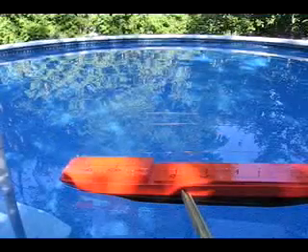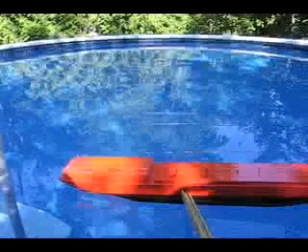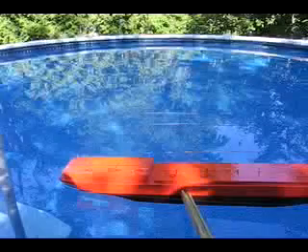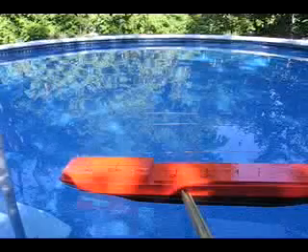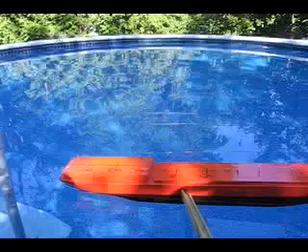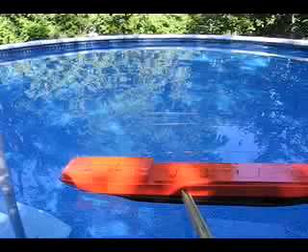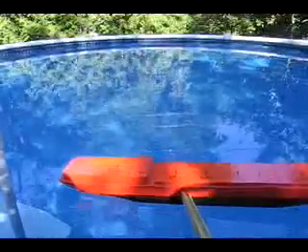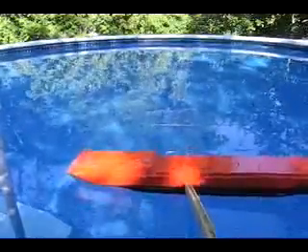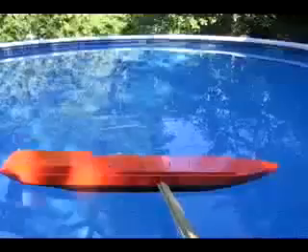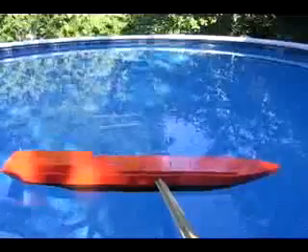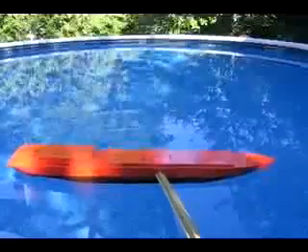The starting point of the center of lateral resistance is the center of underwater surface area, which is normally close to the center of gravity of the ship. The position of the center of the underwater surface for one ship is mainly affected by the trim. A trim by the stern moves the center of lateral resistance point more aft. A trim by the head moves it more forward.